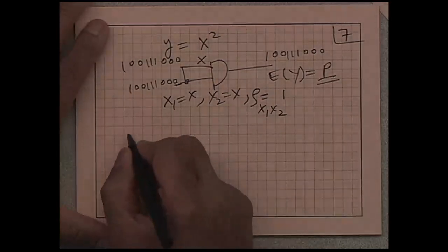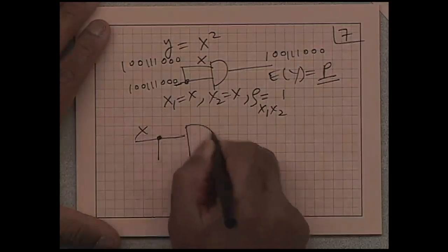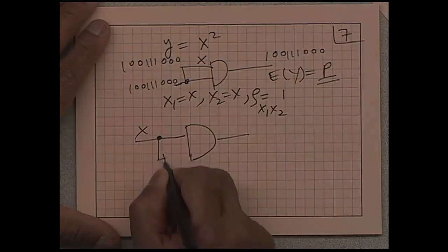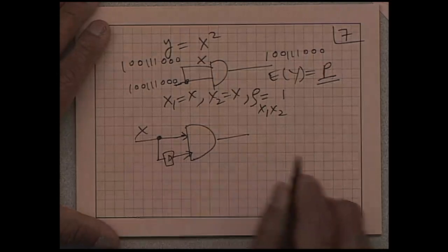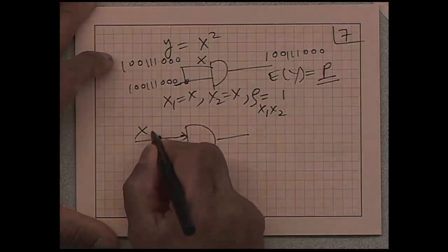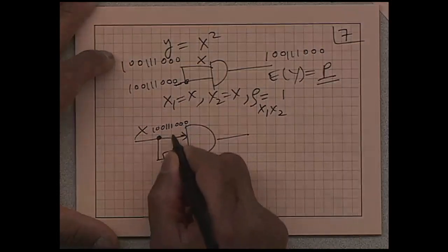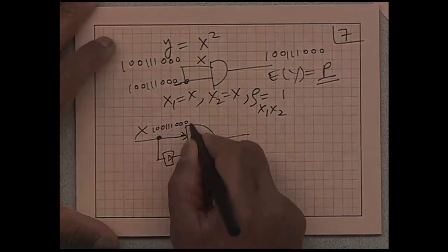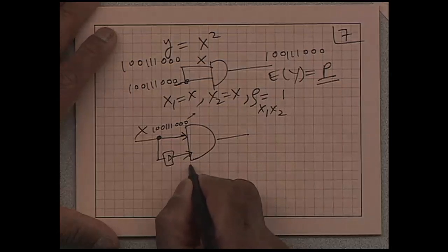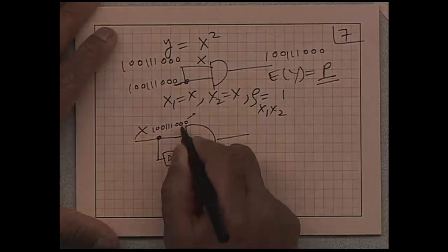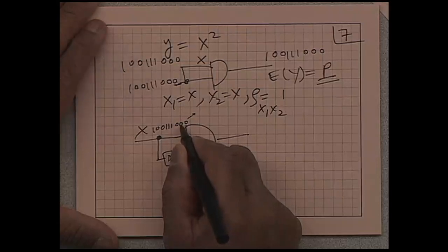So what is the solution to that? The solution is you take the x to one input, but decorrelate by delaying this by one sample. So when this is 1 0 0 1 1 1 0 0 0, shift right by 1, and you can throw this 0 away, and then this becomes, so in clock cycle 2 I have 0 here.